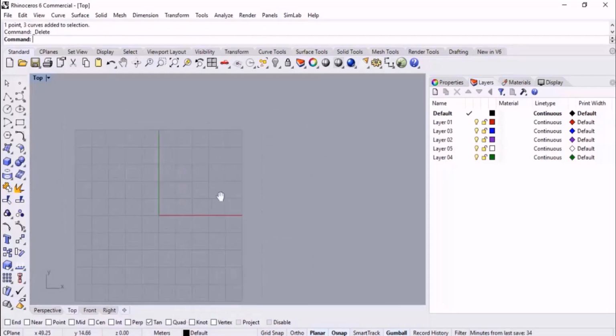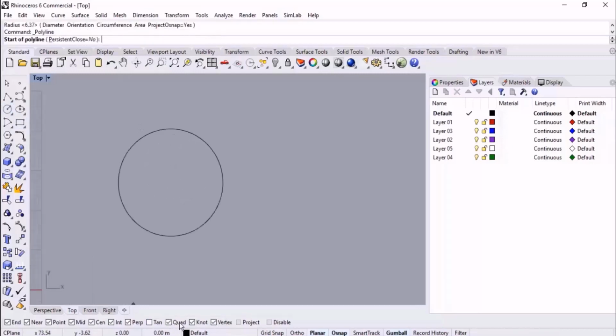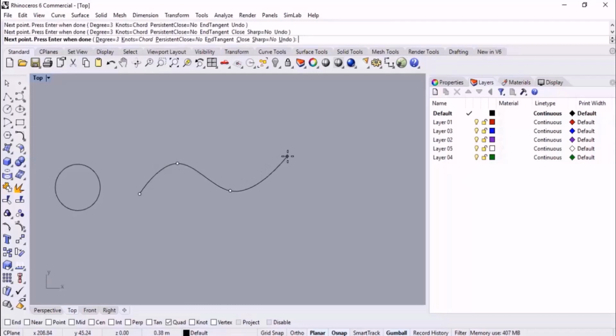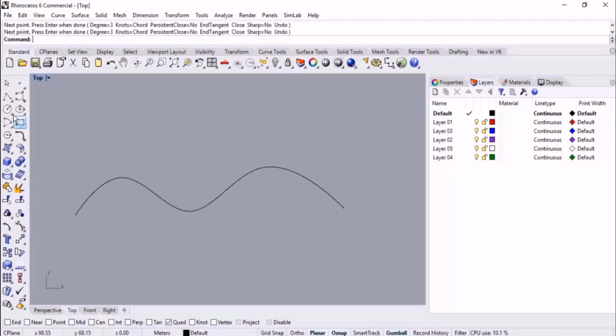Let's talk about quad. What do you think about it? As you know from AutoCAD, when we divide a circle into 4 parts, each of the divided parts is called a quad. Actually, this is neither wrong nor complete. Here, if we had a circle, let me activate the quad. These are the quad points or quad snaps of the circle. Very well, but if we had a curve, let me sketch the curve to give you the next example. You will see that the quadrant or quad is the snap to the point on a curve that is at the maximum x or y point relative to the current construction plane.